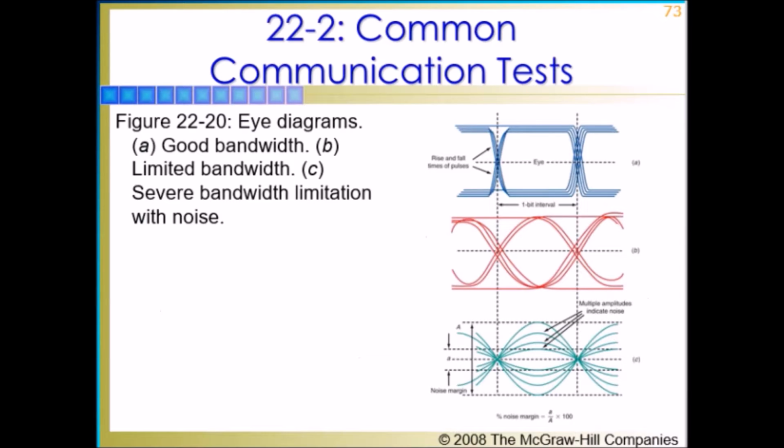This figure shows a serial pulse train for an alternating binary series of 1s and 0s that is applied to a transmission line. The transmission line, either coaxial or twisted pair, is a low-pass filter and therefore it eliminates or at least greatly attenuates the higher frequency components in the pulse train. It also delays the signal. The result is that the signal is rounded and distorted at the end of the cable and input to the receiver.